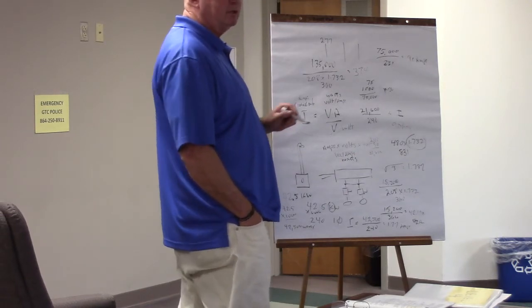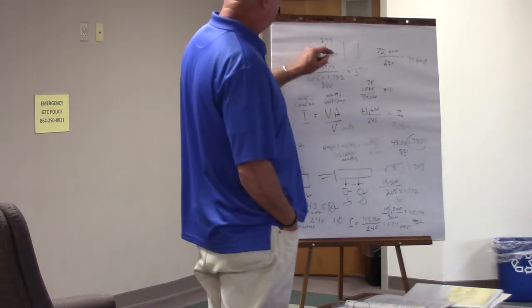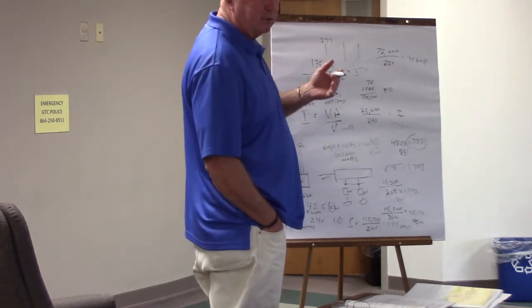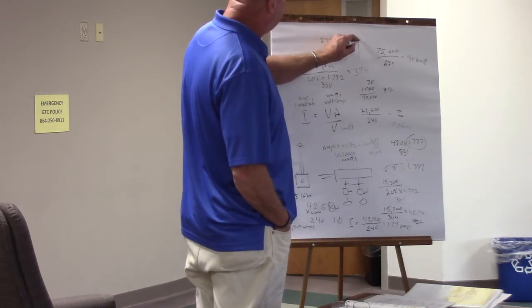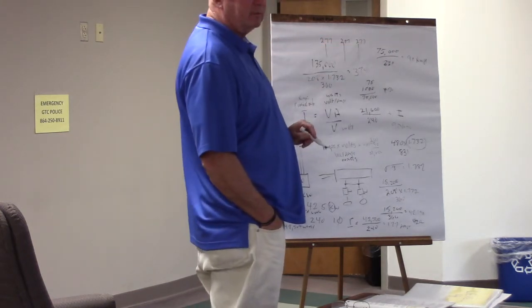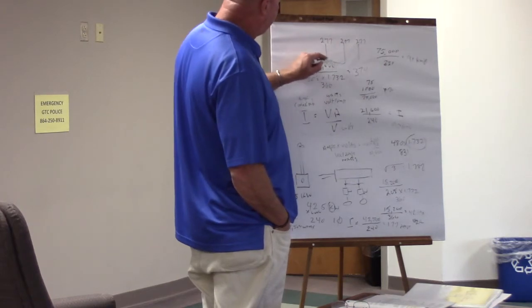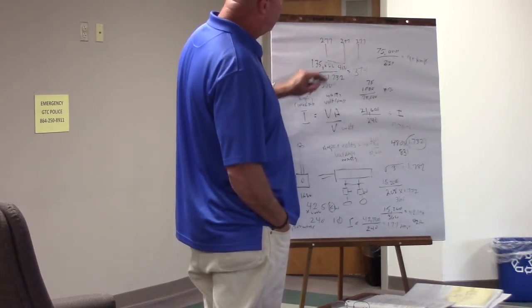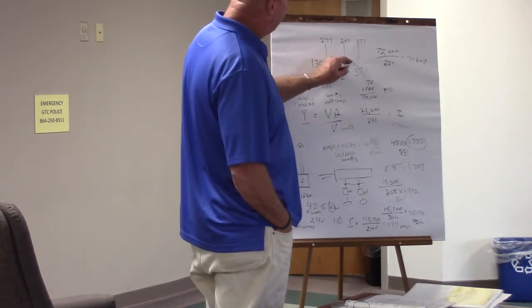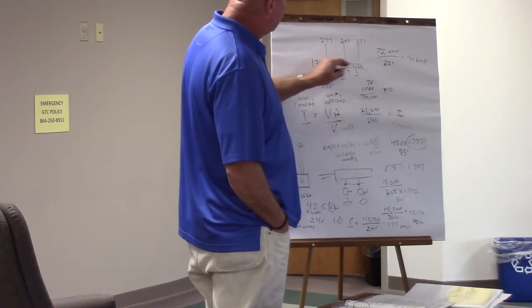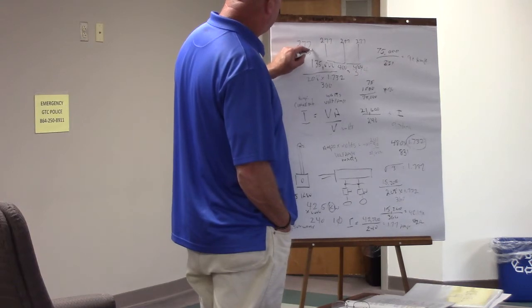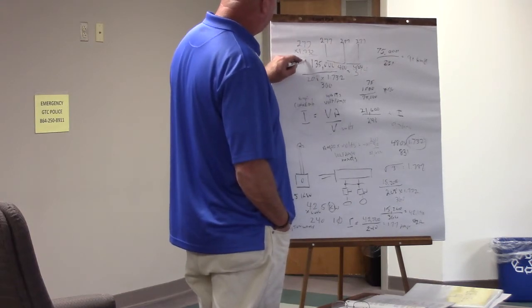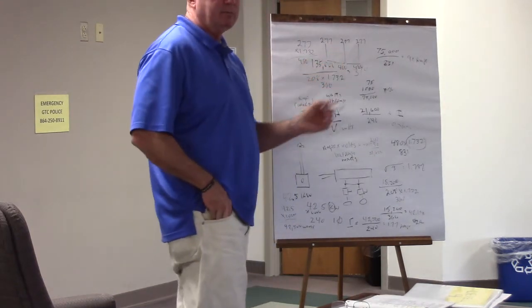$479.77, which is 480. So that's all we're doing. We know that each one of these legs is 277, but when you read between the 2 legs, you get 480. And 277 times 1.732 is 480. So that's where that's coming from. Makes sense?